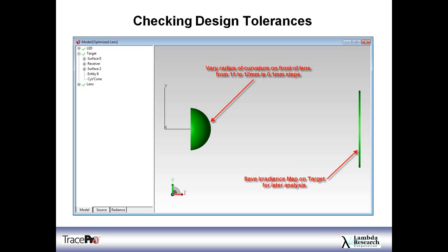Reverse rays is a reverse ray trace, so that would be tracing back from a target, so probably not what you want to do. Oh, so it comes out of the wrong side of the LED. I'd be looking at which surface of the LED die you've applied the surface source property to. The rays should be coming out on the outside of the surface.